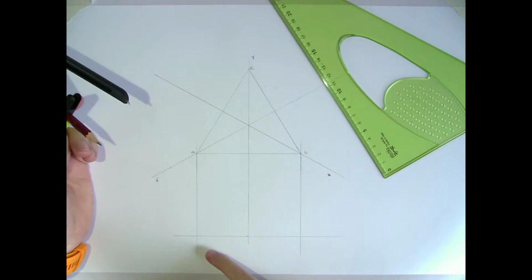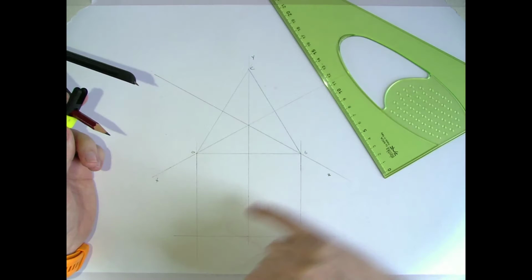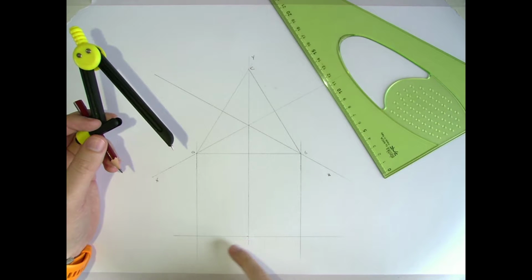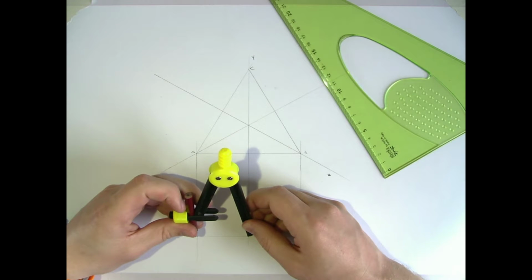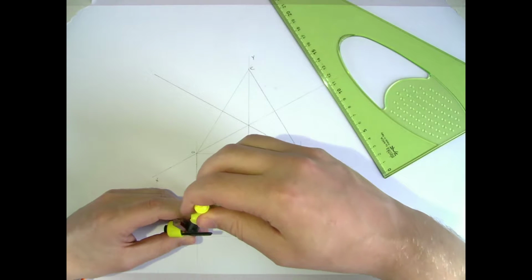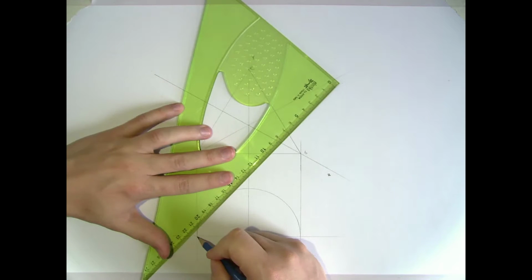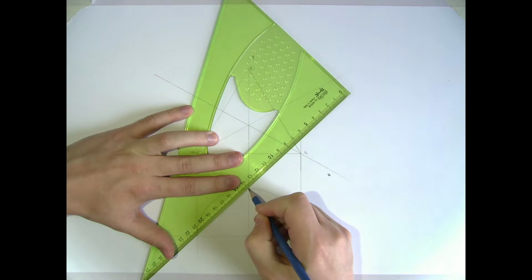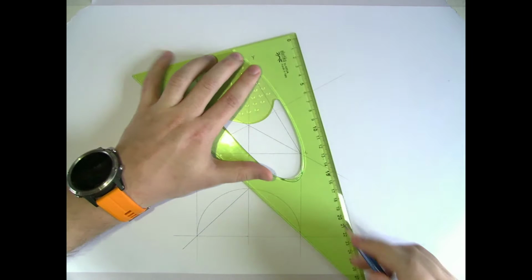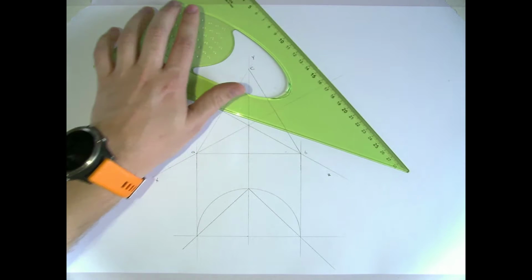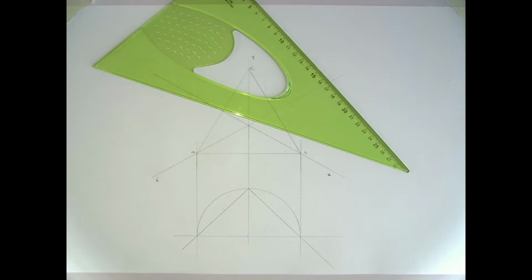So I projected the lines from A and B, extending the Y-axis down. Where the Y-axis intersects this line down here, which is halfway, I'm going to draw a semicircle. The semicircle will go across and touch both sides. From there we're going to create our 90-degree angle inside the semicircle, from this point out that way, and the same going the opposite way. These lines end up at 45 degrees because of the orientation of it.